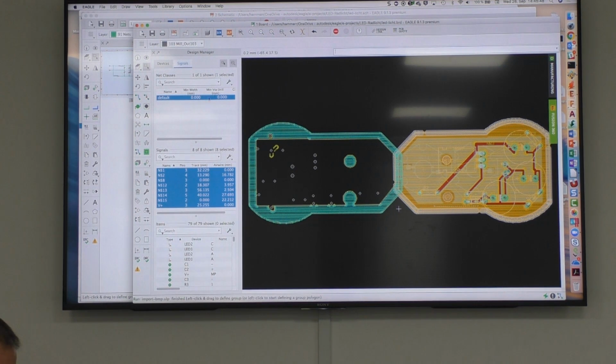Okay. So that's about ULPs. And the other thing we have is the script files. You've seen I've sometimes typed something in the command line, and of course each command I'm using in Eagle, if it's add or wire or name or whatever, copy or paste, you can also type it always. You can create a schematic and a board in a text file, in a script file. And if I look into script files,